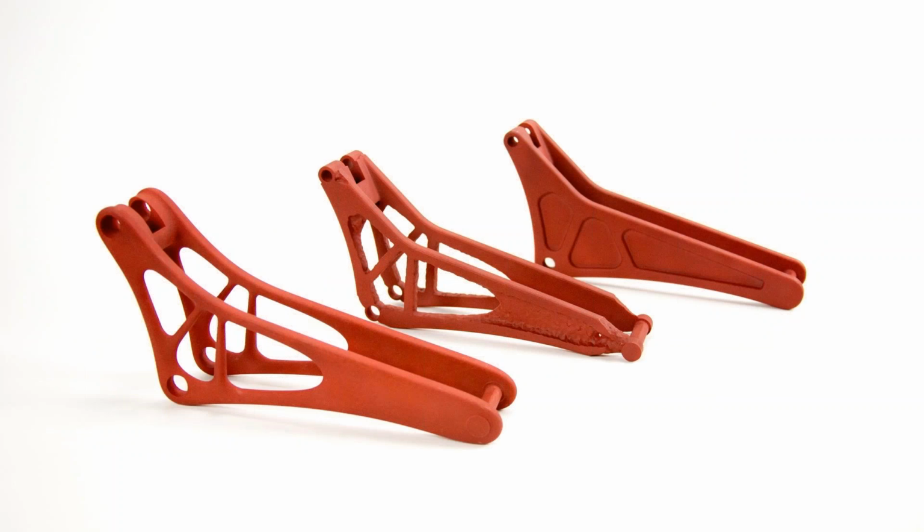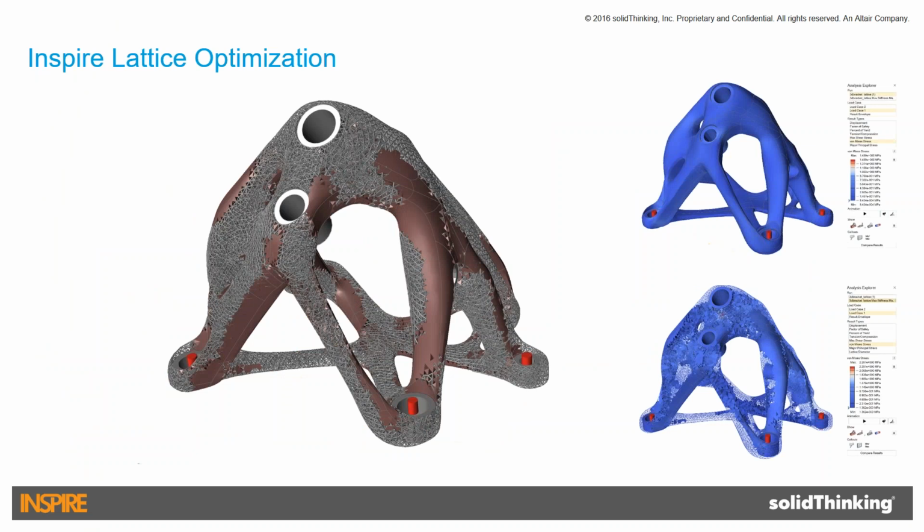This is a bike rocker arm, another example of how Inspire is being used today by our customers. I was talking about the lattice optimization. Let's go back to the lattice optimization again. You can see on my screen, there is some lattice structure and there's some solid, this brown color part. So it's kind of, I would say, 20% filled with solid elements. That's what this particular design needs instead of 100% lattice. If I go 100% lattice, there is a good chance it will fail.